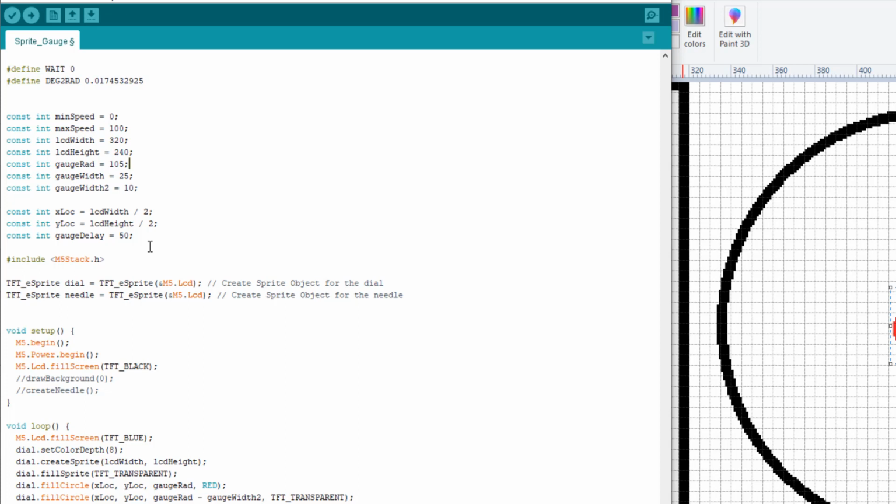There is also something that we should consider. In some displays, we'll be able to build the pixels outside of the actual display area. It'll store that information in a buffer, which allows you to predefine and scroll things from one side to the other a little bit easier, because you can build some of those pixels outside and just shift or translate them. Again, that's outside of what we're doing here, but just a couple extra notes of things you can do, and steps that we took that may or may not be needed, like defining the width and the height of our LCD.